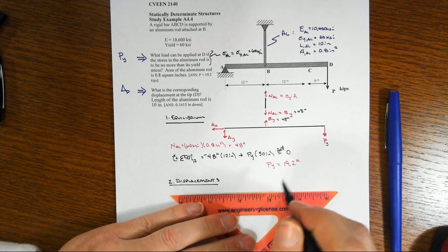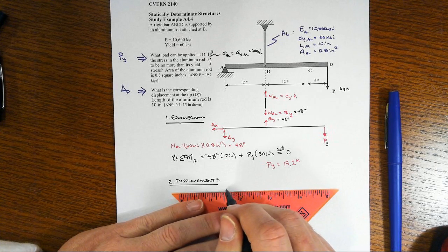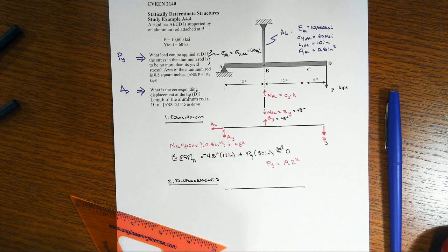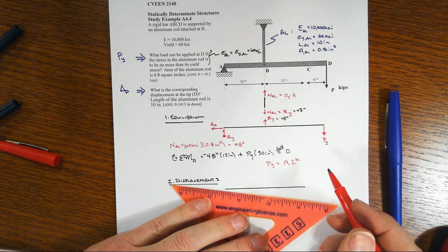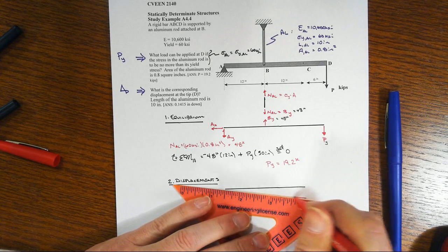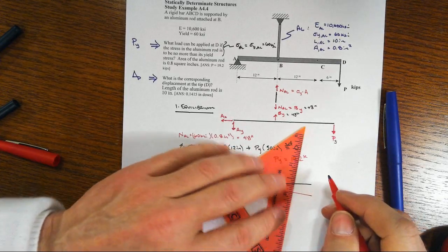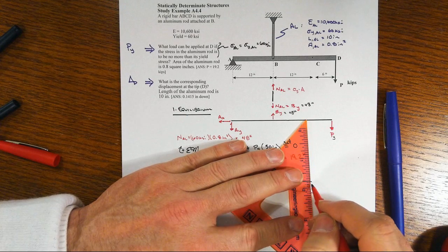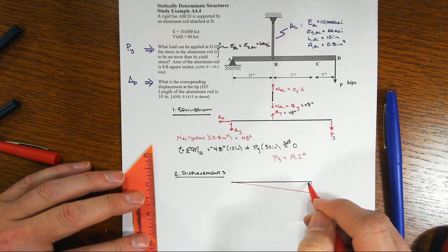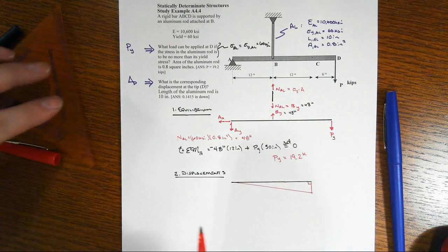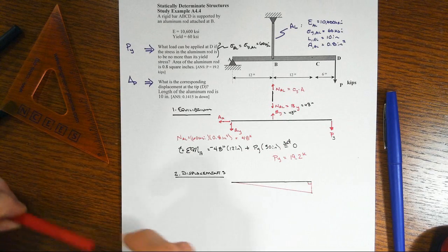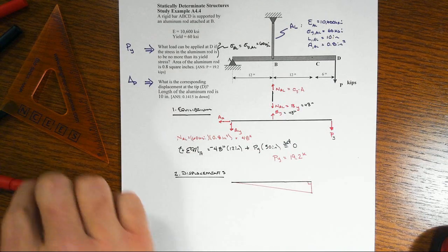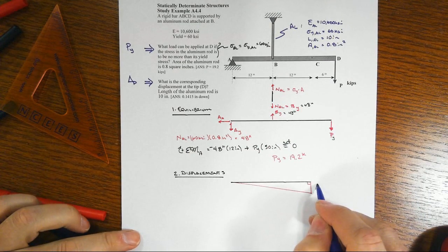So our bar is rigid ABCD, and after it responds to the load, it's going to pivot about point A. Remember, small deflection theory or first order theory, we're going to ignore that that's actually an arc, making a small error, but the differences will be so small and minor that it won't have any practical significance to what we're trying to accomplish.